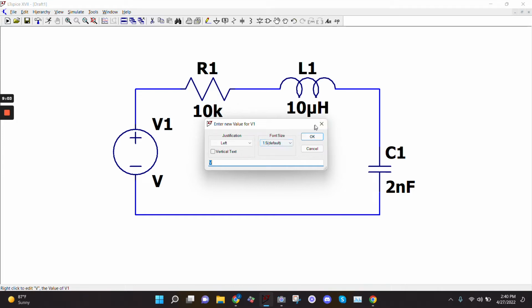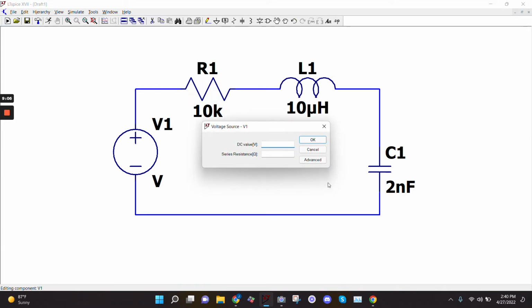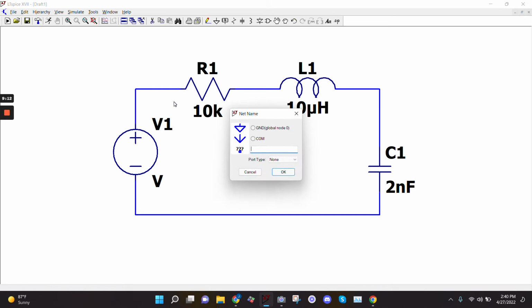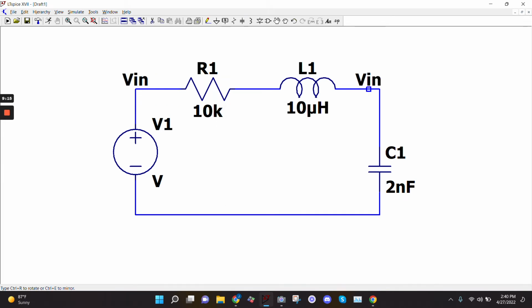And then what I'm going to do is something called AC analysis, okay? This is something we haven't seen before, but I'm just going to do it for the reason of determining whether these are reasonable values. What an AC analysis does is it sweeps this circuit over every frequency within a range that I give it, and it looks at the ratio of my output to my input over all of those frequencies. So I can pick a frequency where I want to operate because I want my output to be 1/2 of my input or something. You'll see what I mean. It's probably sounding ridiculous right now,